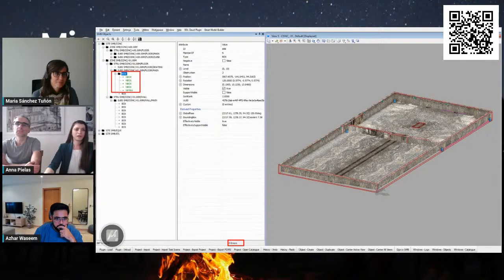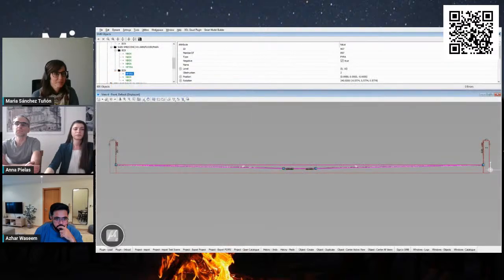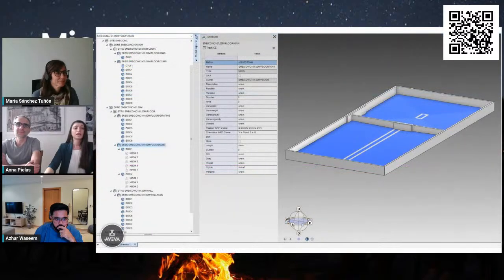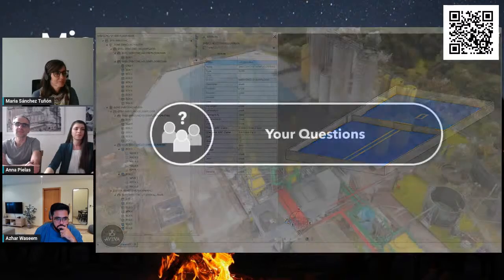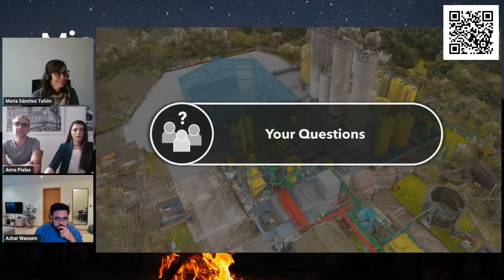As you can see, the number of errors found in the model changed during the process, and now our model is free of errors. The cutout can be fit precisely thanks to good point cloud display and the ability to clip the cloud and the model in MicroStation. The entire model is now imported into E3D with the hierarchy and the definition of the negative solids preserved.